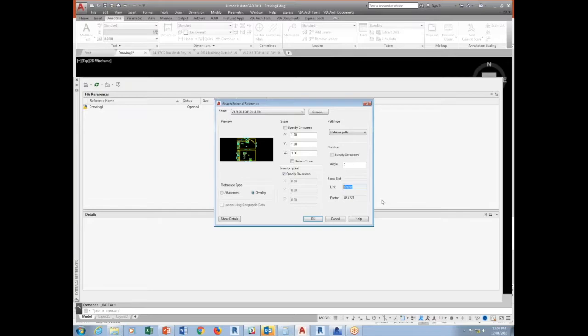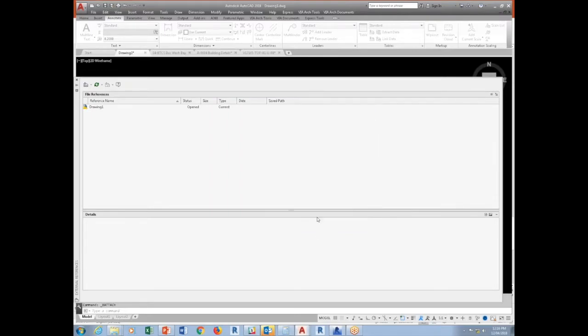So you no longer have to scale everything, because I know that in some cases someone actually scaled this drawing by 1,000 because they said, oh, it's in meters, they want to scale it up. In this case, don't do that, right? Just keep it to the units, and then just watch out for this, okay?